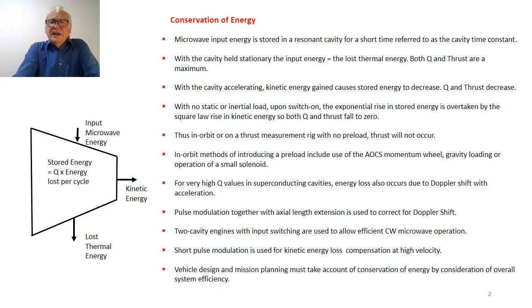In this particular case, with a fixed cavity, both the Q and the thrust that is produced by the cavity are a maximum. Once you allow the cavity to accelerate, the kinetic energy gained causes the stored energy to decrease. Therefore, the Q and the thrust will decrease. And this is simply EmDrive obeying the conservation of energy.